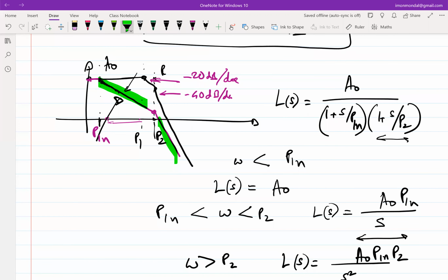That is the intuitive reasoning, but it is not mathematically proved. If you can ensure that around omega u loop your loop gain behaves like an integrator, the closed loop output response will behave like a first order system.